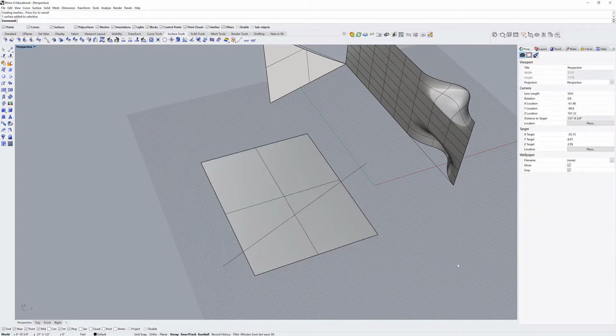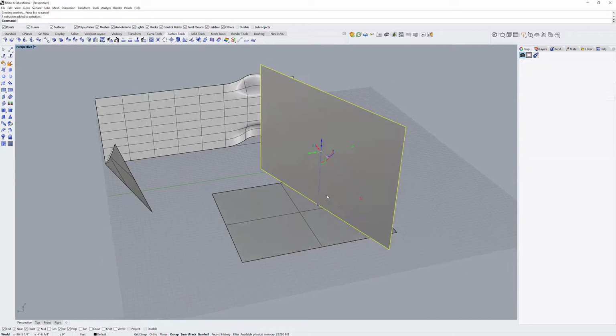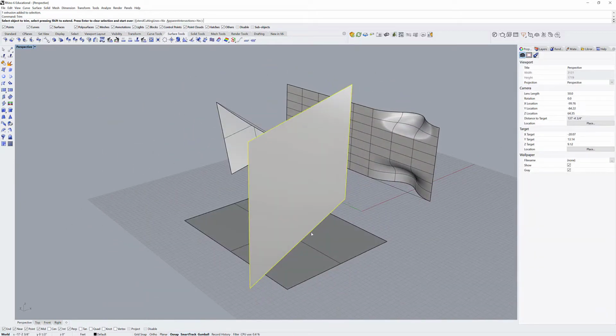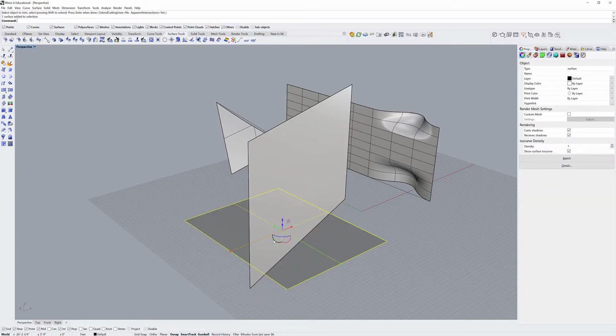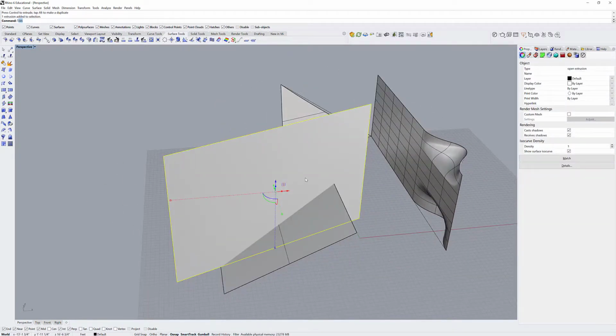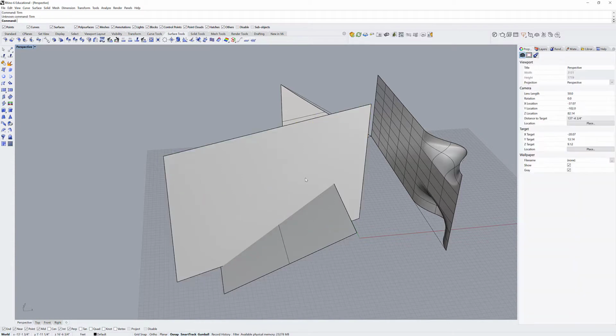It doesn't have to be just lines that you're using to trim, so let's extrude this curve to create a surface. I can trim with the surface, and wherever it will intersect, we'll cut it. So if this is perhaps maybe a little bit more complex, I can use trim. So let's select nothing, run trim again. You can see what my cutting object is.